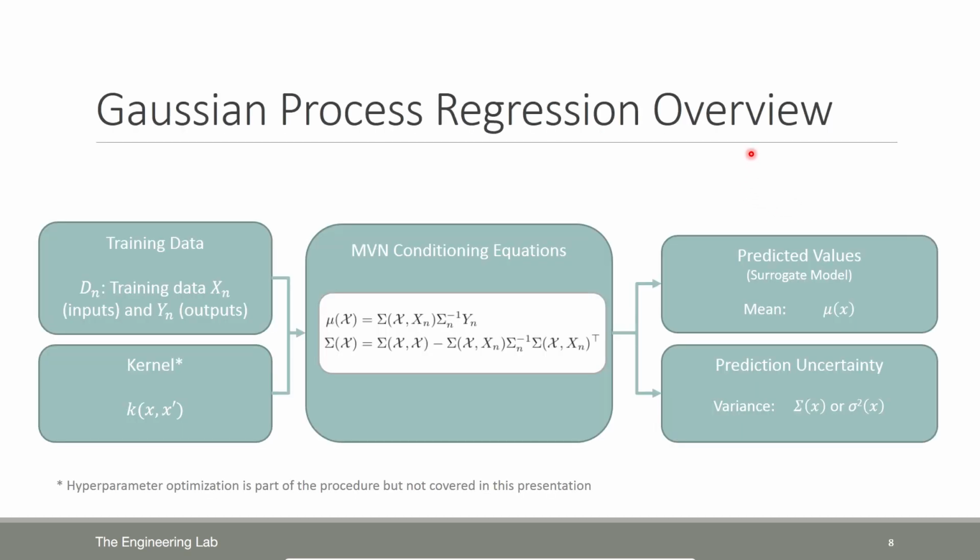So the first goal is fitting the model. Here we are using the Gaussian process regression method to yield our surrogate model. This surrogate model can be used to predict the output of Nastran at different points that you pick. So what's the process for this? Number one, you obtain your training data. If we go back to the 3-bar truss example a few slides ago, we're going to take that finite element model and run it at different configurations for the cross-sectional areas. At each configuration, we're going to collect the outputs: the weights, the axial stresses, displacements, and any other response that we want to predict later on. So here, the X is every different configuration of your inputs or FE model, and then your Y corresponds to all of your output responses, the weight, stresses, and so on.